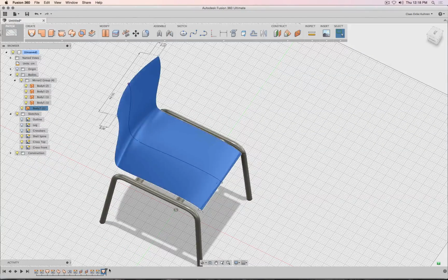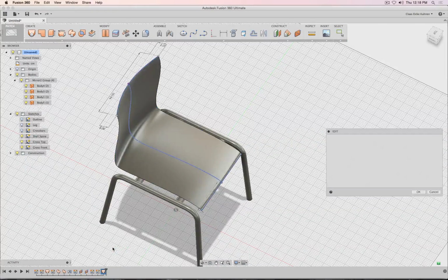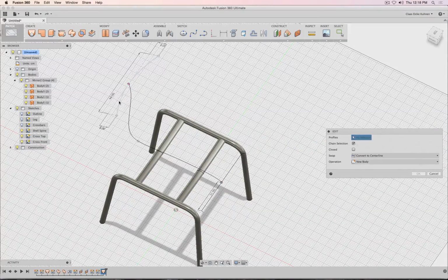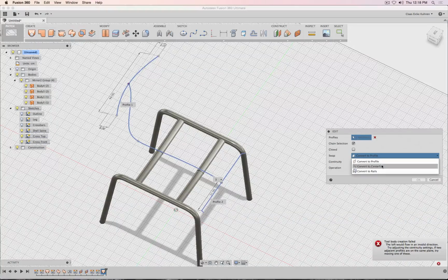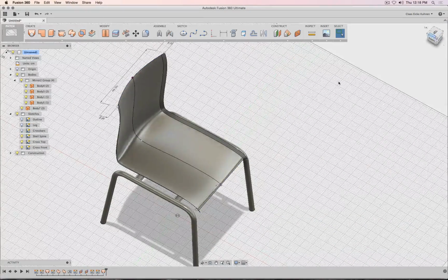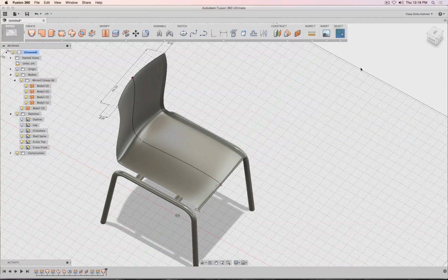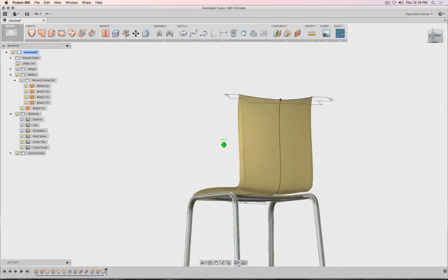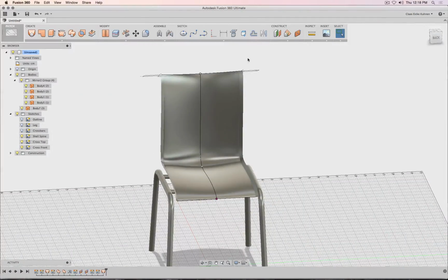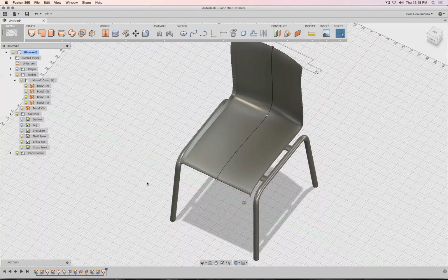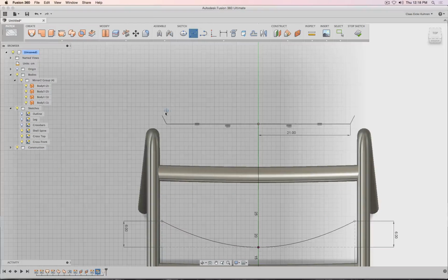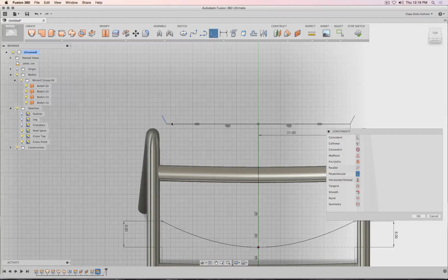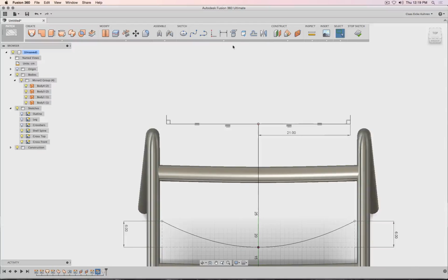So edit, there, okay. So this profile to this profile along this one center line. Okay, just show me shaded. Yeah, okay, as expected. It's really tricky to have a rounded profile and a linear profile, obviously. Okay, let's go back to here, and I'm going to punch in another spline there, there, and there. Actually, hold on, before I do this, I want this one to be perpendicular and then also dimensioned.